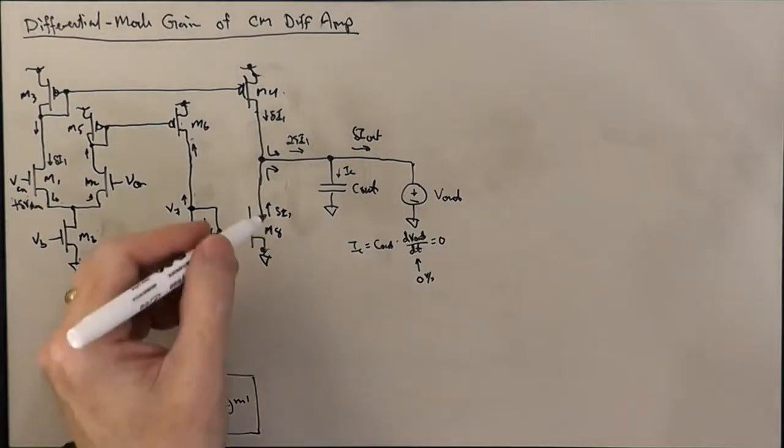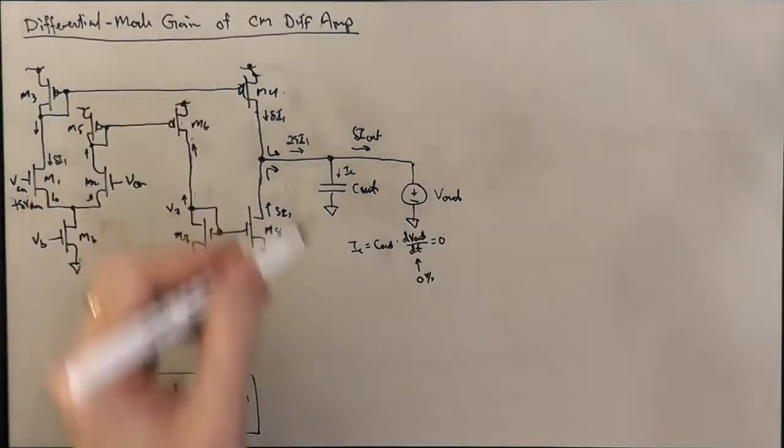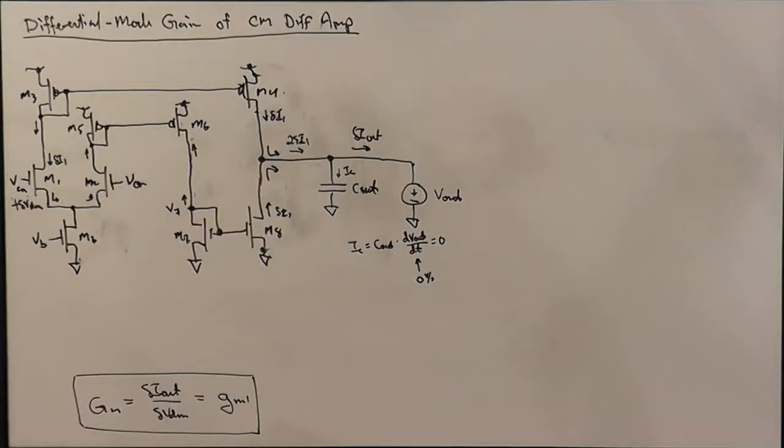Just like we said that if we had early effect resistors here, because the voltage has to change in order for there to be a change in the current flow through the resistors, and we're holding the output voltage fixed, not allowing the voltages to change, the early effect resistors can't change the amount of current flowing through them. And so there's no delta I flowing through them.